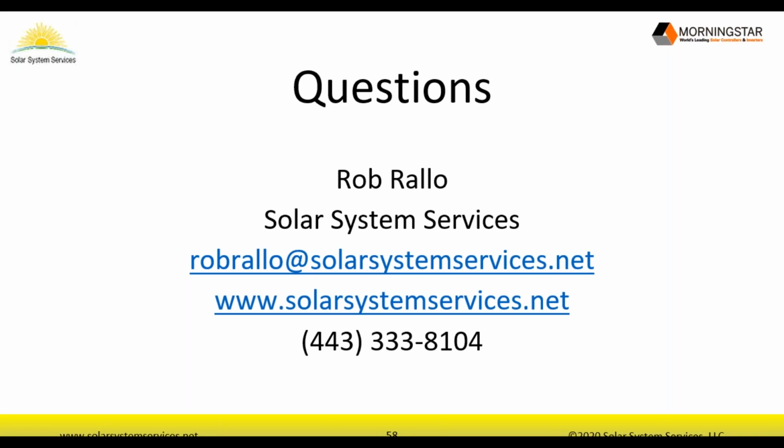We can refer you to some application design and support documents from some of the enclosure companies that will allow you to calculate heat generation in watts. Morningstar can help you with that as well. And you'll often find that even in just a vented enclosure, your heating is typically fine if you give it adequate space above the product. It's really only in high power 10, 20 kilowatt telecom enclosures where we ever run into active cooling needs, where there's an air conditioner or fan that has to force air out of the actual enclosure.